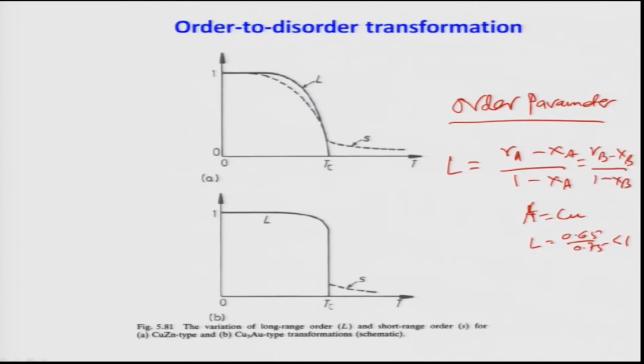So, in the X-ray diffraction patterns, for the ordered structures you are going to get X-ray reflections, because now the atoms are occupying specific sites, and because the atomic scattering factors are different for gold and copper. So, there will be diffraction intensities which are not allowed by the FCC. I cannot go into the details of those, because it is a part of X-ray diffraction, but it is possible. So, by looking at the intensity of these reflections which come because of the ordering, one can measure the long range order parameter.